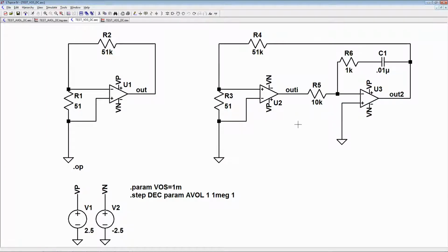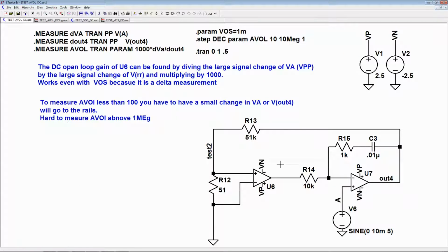to verify our offset voltage. Now what I would do is that we need to start developing test boards and test circuits, you can just use any old op amp. I might even recommend using the 741 because it does have such a large offset voltage. And to make this circuit, you're going to need to make a board and then a test protocol, so that you could take pins and plug it into that board to test the op amps when they come back. Then the other thing is the open loop gain, and it has the same kind of circuit. Oh, just one thing.